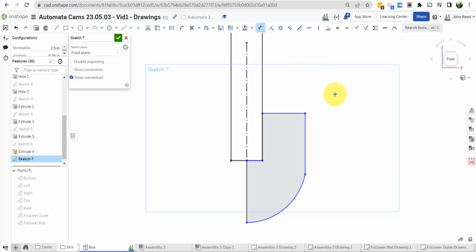Okay, so let's put some dimensions on here. I know this distance here from here to here. I want that total diameter to be 0.5. So I'm going to bring it on this side, and you can see it turns into a diameter. But really, I'm doing the distance from the center line to here. So I'm going to put it over here, and watch, you get the diameter. I want that to be 0.5. Okay, so that's going to make this part a 1/4 inch, so it's 0.5 total. And then this distance doesn't have to be huge. Let's do 3/16.